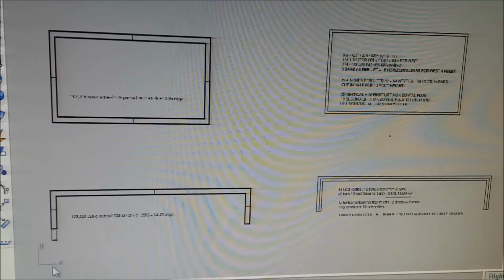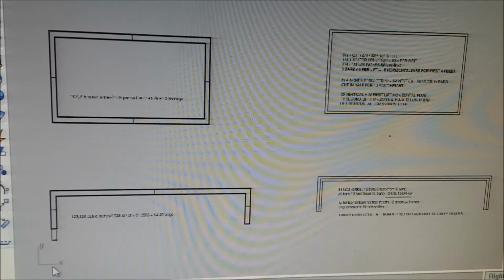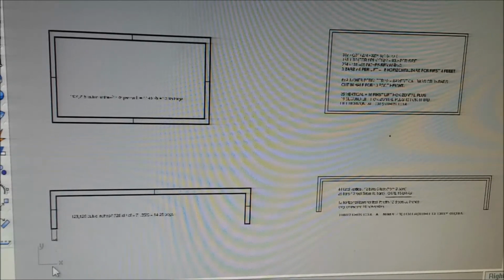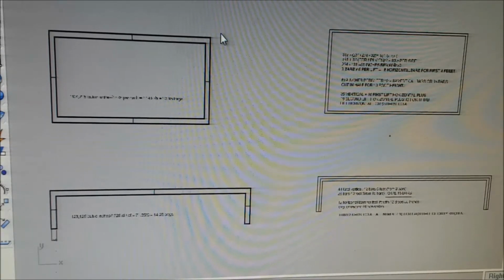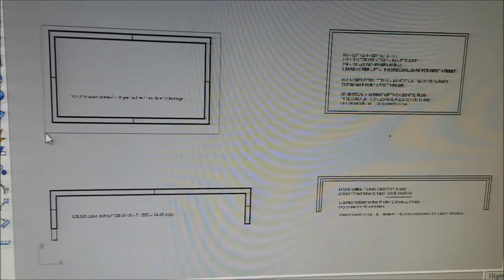The concrete itself is a volume calculation. You're buying your house by cubic feet or cubic meters. There is so much sand per cubic meter, so much gravel per cubic meter. The bags of cement are a cubic foot, 40 pounds. So we're going to do concrete and rebar and sand and gravel.